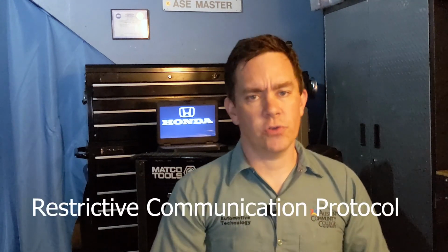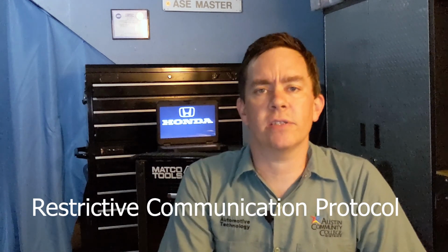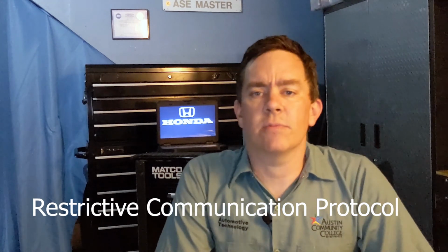So in this video, we learned that a short in a communication line disables all communication across the network. We learned that an open in a communication line only affects the control unit isolated from the network. And we learned that a fault in the powers or grounds or internal to the control unit will primarily affect the control unit with the fault. We didn't discuss some of our newer control units, which use a design called Restrictive Communication Protocol. That design disables communications across the network regardless of the fault type, and that prevents us from using symptom-based troubleshooting on those types of vehicles.